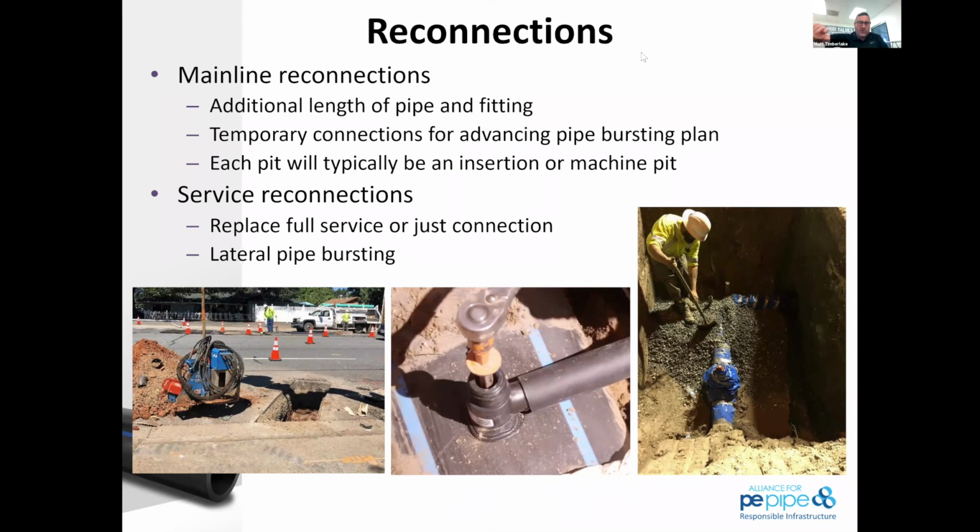This would be an alongside service where you can then burst back over to where that pickup truck is. So now you burst the main line, and you burst the lateral back under those travel lanes, all through that small lateral pit.